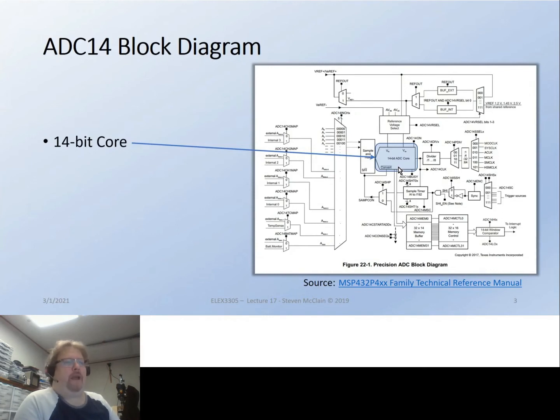Where the sample rate starts to matter is if you were trying to record audio or video, audio specifically. Your sampling rate would determine the highest frequency that you could record. And so sample is the time it takes to convert, or the time it takes to send one bit? That's how wide one of the steps is. It's not how tall it is, it's how wide it is. Only so many steps per second. Each one is a sample, like you're slicing it up.